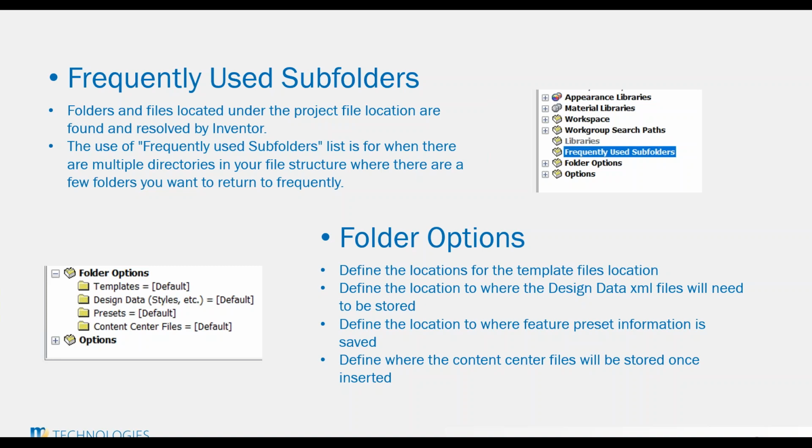The 3D modeling data needs to be saved as, in other words, a part file. So it is actually going to save that into that content center file path that you see down the bottom. And again, all these defaults have controls in the application options files tab, where you can set them.